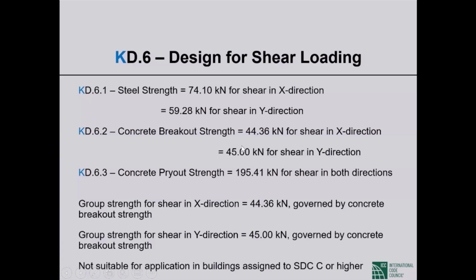So the shear strength for both X shear and Y shear is concrete governed strength. So this group is not suitable for design category C application.